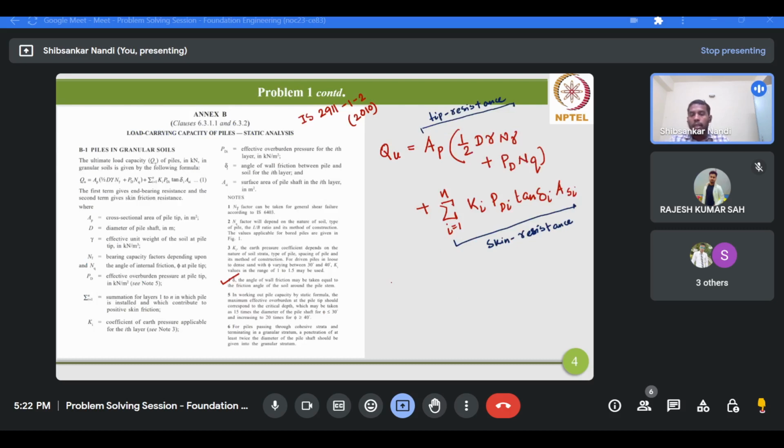Okay, now what is critical length? So if this is the whole length of the pile, and if this pile is subjected to some point load at its top, as you can see, first the skin friction will be mobilized, and after that as the load is increased, the remaining load will be supported by the point bearing resistance, that is the resistance given by the pile tip.